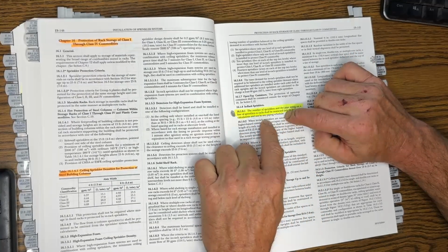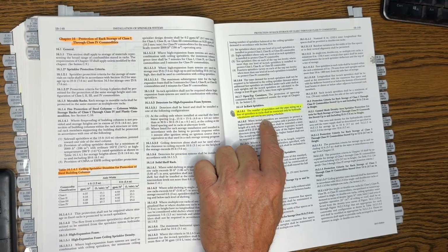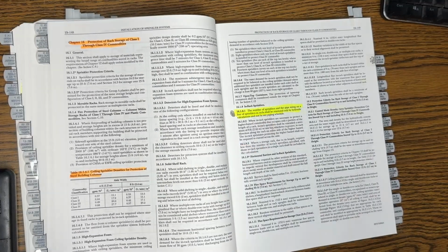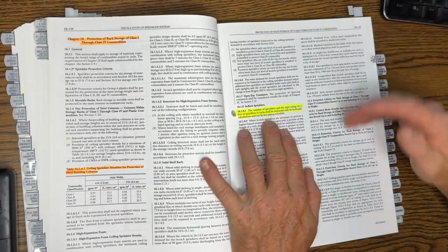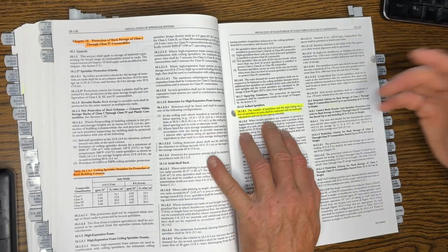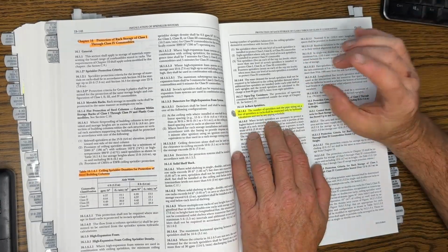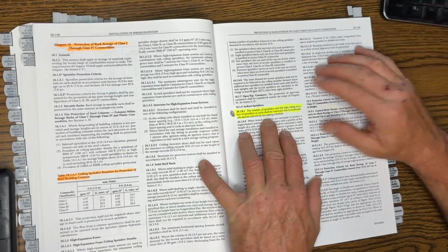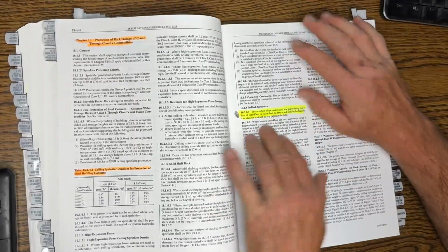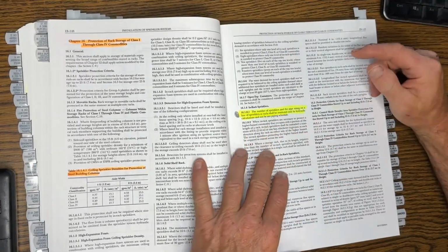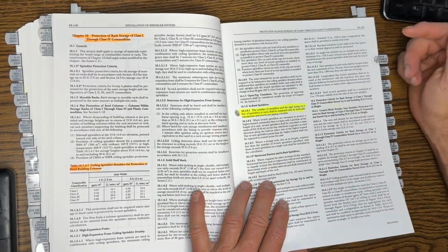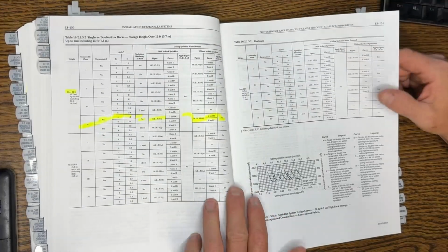Just to explain, piping schedule has a specific definition. It's where you have like 2 heads on a 1-inch pipe, or more heads on 1 1/4, 1 1/2, etc. It's based on the delivery pipe size. That's how they used to do it. You can't actually do a pipe schedule anymore. It has to be hydraulically calculated. Everything's hydraulically calculated anymore, so it's kind of a dumb question.